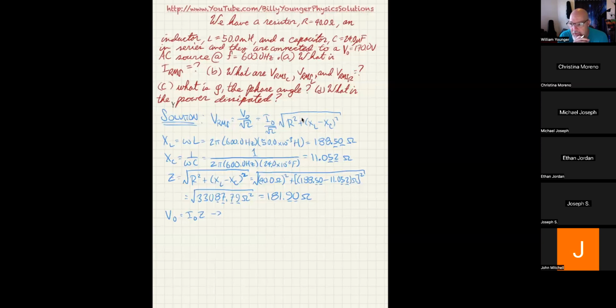Okay, thank you. I know that's not a very happy or good answer. I know that's not clear. I know that's not the wonderful Shangri-La moment that you were hoping for. But what we've discovered is that when I measure, for instance, the voltage across an inductor in an AC circuit, assuming you're measuring with a multimeter that measures RMS, you're going to get a VRMS that's consistent with the existence of this impedance. So at the end of the day, you can just say it's this way because evidently experiments said it was going to be that way.